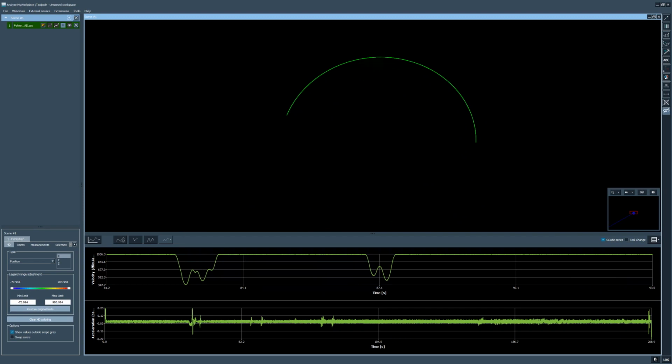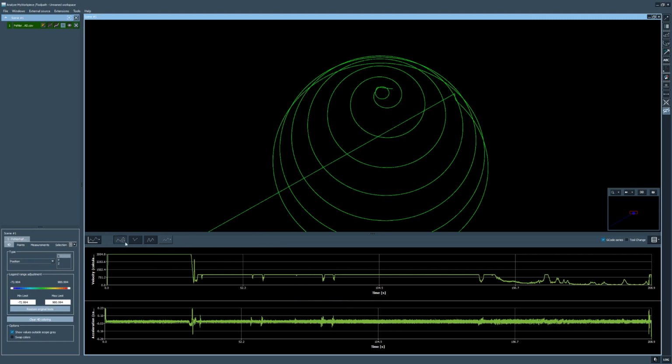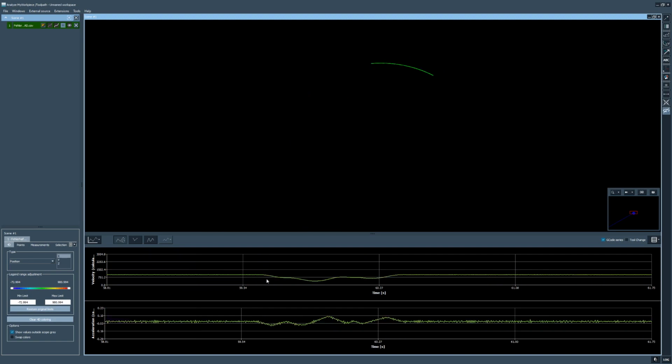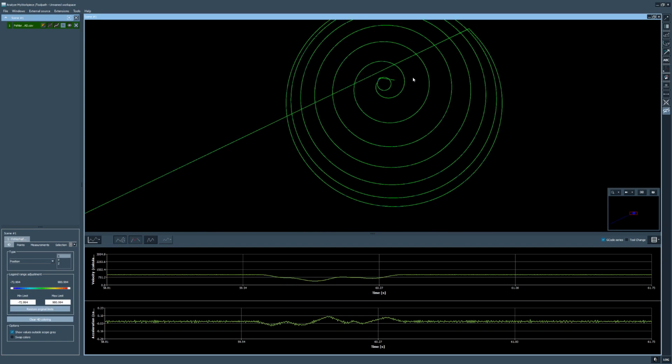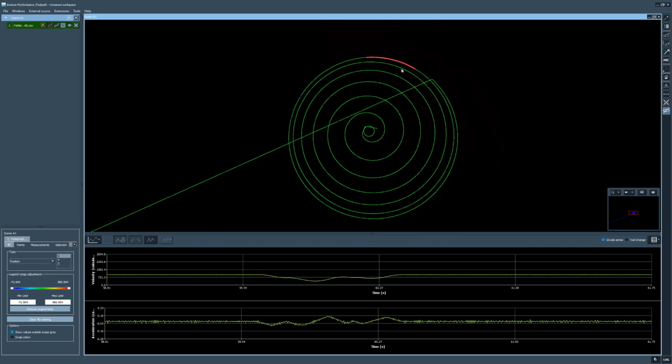what happened now is that the velocity graph got zoomed into, but not the acceleration graph on the bottom. So in order to do so, let's restore the original view first. Let's click this button. Now the two graphs are synchronized. So if I want to zoom in here, now I see the velocity on top, the acceleration on the bottom, both synchronized, and if desired, the point cloud selected. If we click this, then we see it with a selection. So this is done with the synchronized graphs on zoom.